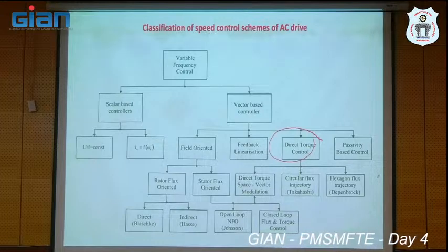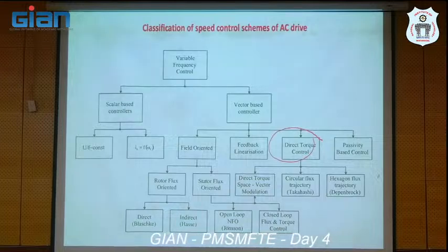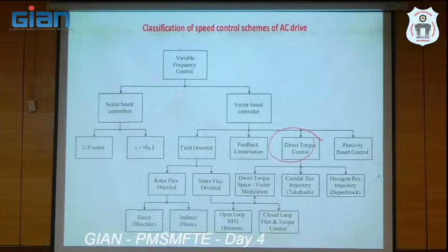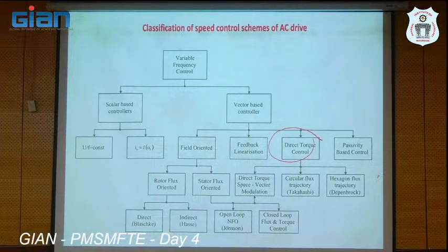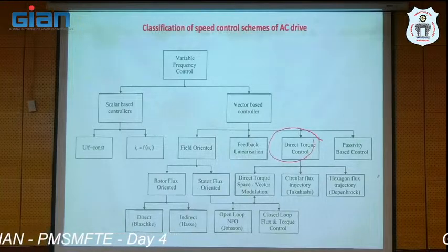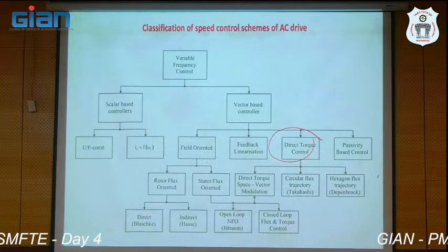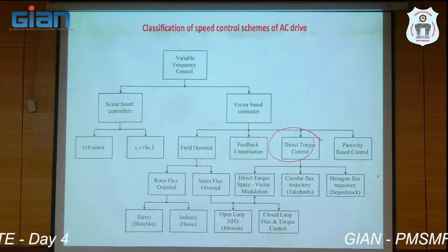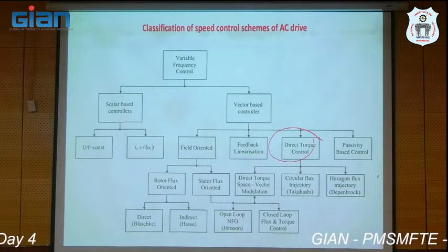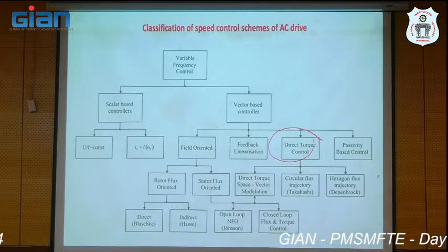If you observe, there are a lot of parameters involved in the system. Whatever parameters we adopt to derive the rotor flux position, those parameters will practically change. Inductance will change. If the load on the motor shaft increases, inductance will definitely be affected. Inductance decreases because of the saturation effect. At the same time, resistance also changes because of the heating effect.